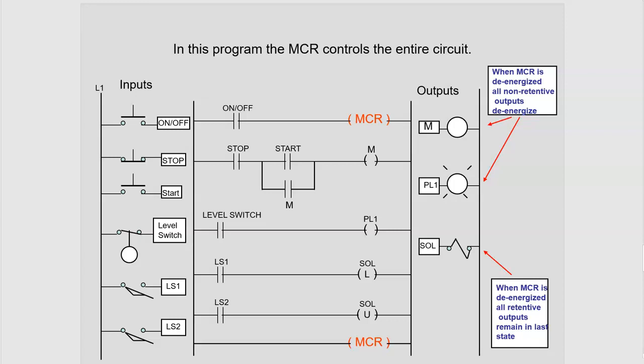You don't want to have some machine like a fan or some unknown machine in the on position, and then when they flip the main power on, this thing turns on. It can be a dangerous situation. I'll leave it to your imagination as to what can happen. So typically, you don't want to put retentive outputs in the MCR zone unless you really have a specific reason for doing so and you know what you're doing. Otherwise I would highly recommend against that.